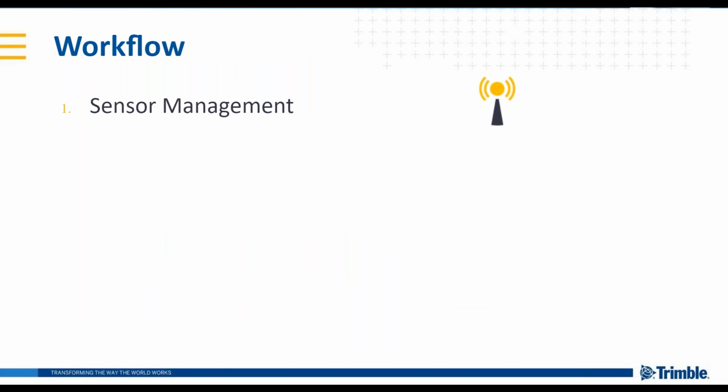So starting with the workflow, and this we're going to cover in detail in the hands-on demo, but to preface it, we'll go over it step by step. With T4D web, first it's all about starting with the sensors and sensor management. And this is about checking the data flow all the way down to the sensor health of all the various sensors you may have on your monitoring project, which could be optical sensors like total stations, could be GNSS, and could be geotechnical sensors and a variety of other data that can come in.